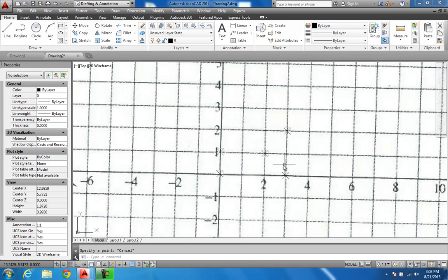However, if you utilize the relative movement, see how this one's always your 0, 0? If you use relative, what it does is, like this point, we're going to go off this one, and it would still be the same as absolute because this is our 0, 0. This would be 3, 0. But after this point, if you hit the at symbol before you do the movement, it turns this point, the last point I was at, 0, 0.